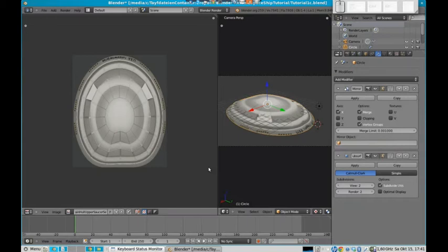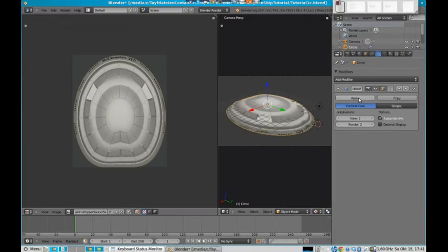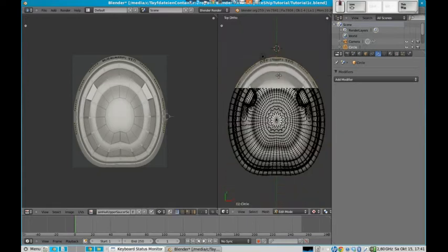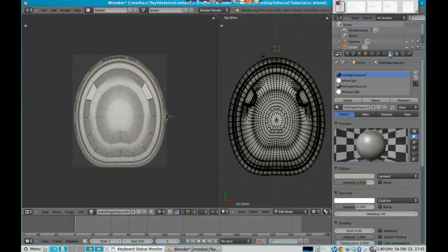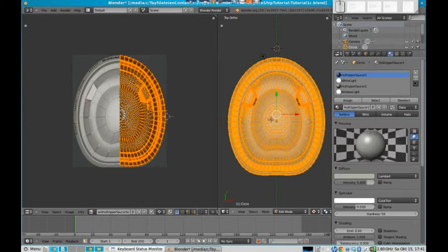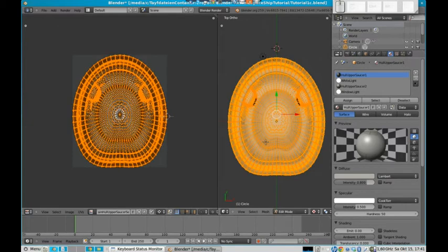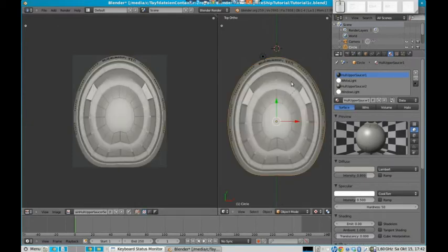And since we will do that at the end anyway, we can actually just ignore this problem, but to show you that this problem will disappear if we apply the modifier, I will just demonstrate that by saving that first, apply the mirroring, and you can apply that too. Then you will see additionally that everything will have much more vertices. So we will just select everything which consists of this material, which is not completely everything. And say W, project from view, ta-da, and it's almost perfectly rendered.